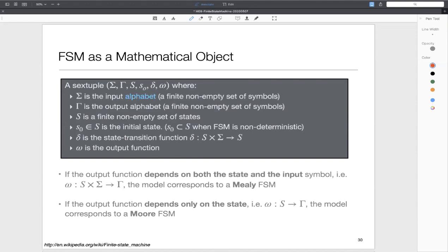I can indeed describe a state machine strictly in terms of the input alphabet set, output alphabet set, the set of states, the initial state, and 2 functions. That's what it takes to describe a state machine. The graphs we are drawing are a representation of it. The hardware we were making for sequential machines is another representation of it.